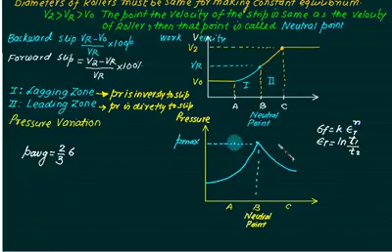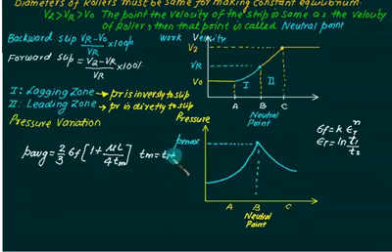So this is our sigma f, that is the flow stress, multiplied by 1 plus mu L divided by 4 Tm. What is Tm? It is the mean thickness. What is mean thickness? It is T1 plus T2 divided by 2. Now you don't require this equation for the GATE examination. They will directly give you the value of P average.